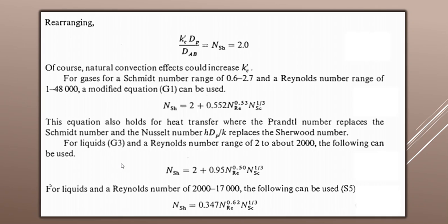Then we have to determine the heat transfer coefficient, and before that we need to know the appropriate dimensionless number to use. And once we have the h, our convective heat transfer coefficient, we can substitute it into our heat flux. In here we have the flux or the molar flux because we're talking about mass transfer. So these scenarios wherein we're using the Sherwood number are for flow past spheres.